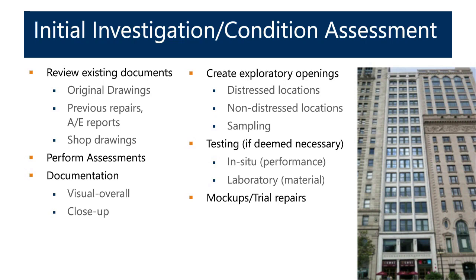May create inspection openings to find out detailing cause of distress. This will more likely get you into the construction documents. And if need be, perform testing, whether in situ or in laboratory, in order to find out what's causing the problem and help design a suitable repair, which then moves you into trial mock-ups and trial repairs.